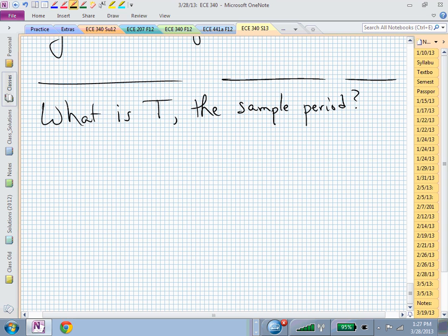You know the eigenvalues of A are the poles of your system. But the more important thing to maybe keep track of is, what's the magnitude of those poles? Or what are the magnitudes of those eigenvalues? Remember, I did the absolute on my poles. How far away from the origin were those poles on that semicircular arc for this particular example? They were 10, weren't they? They were 10 radians per second.